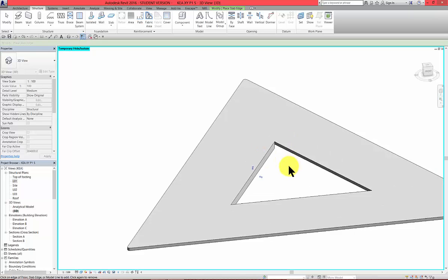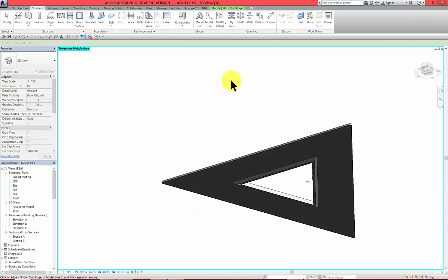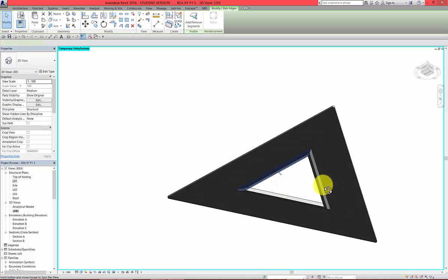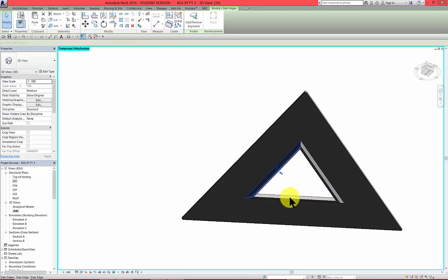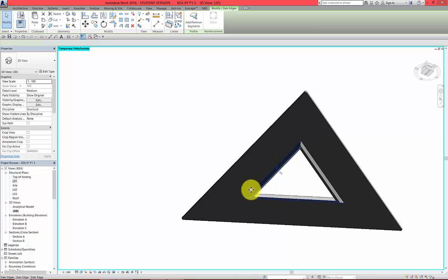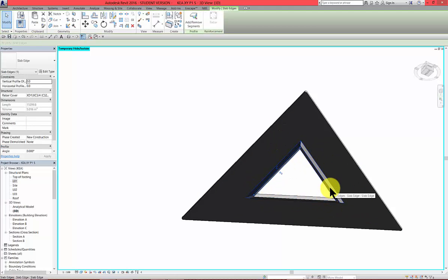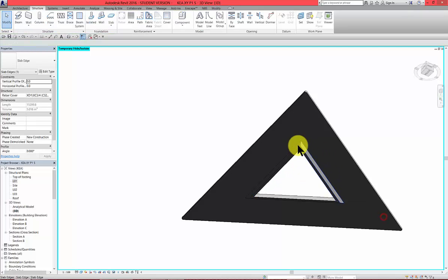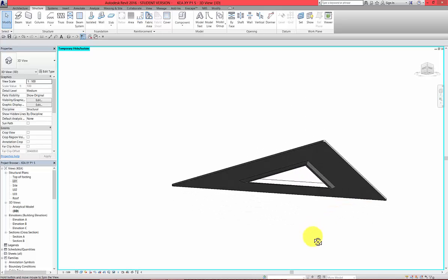So the same now, escape before I press this, then again structure, floor, slab edge, and then click it. Okay, to check if I did it correctly, if you select the slab edge, only one part should be selected. If you select one part and all the parts are in blue selected, that means it's wrong. You need to create it all one at a time.